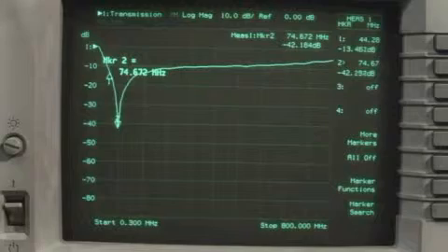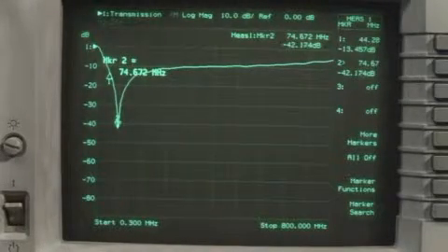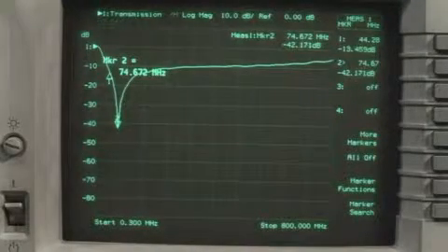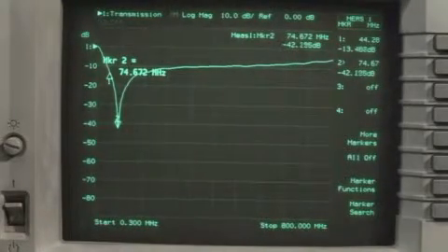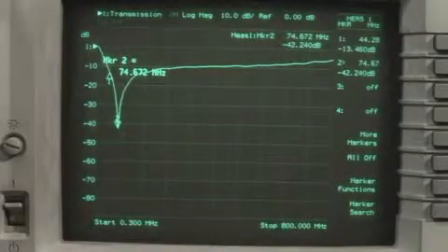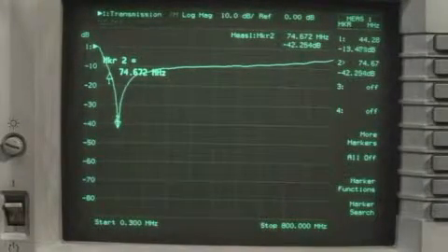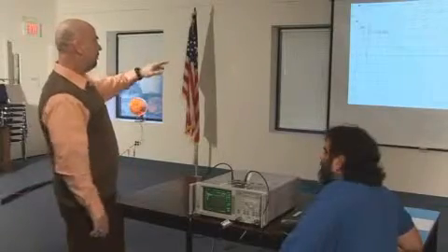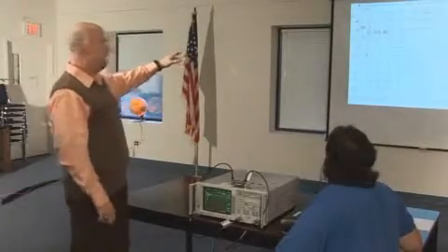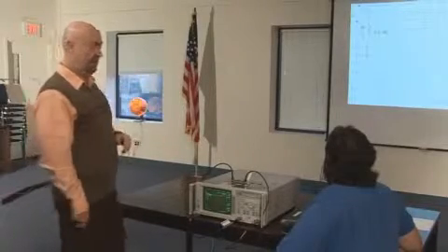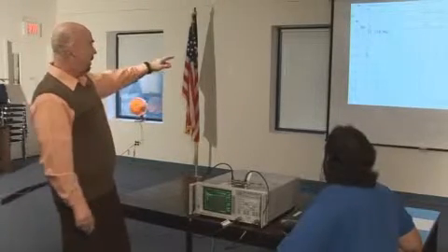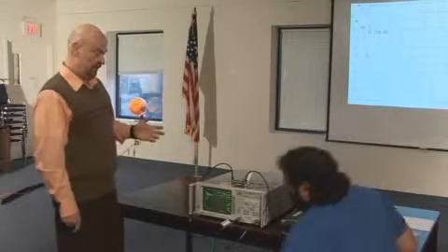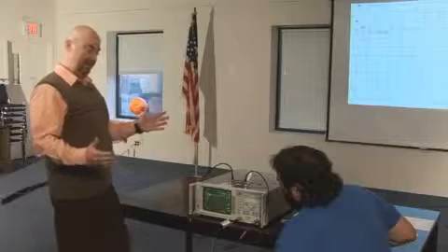So now you come in just for a cursory check to make sure things are okay. You already have 50,000 of these boards rolling down the line. And you come to me, and remember before we were at 43, I said, well, your signal's failed. Well, what happens if you look at the first marker now, where I had 35 before? I only have about 12 dB of rejection. My notch point for this filter has now moved to 72. And you know why, Steve, right?